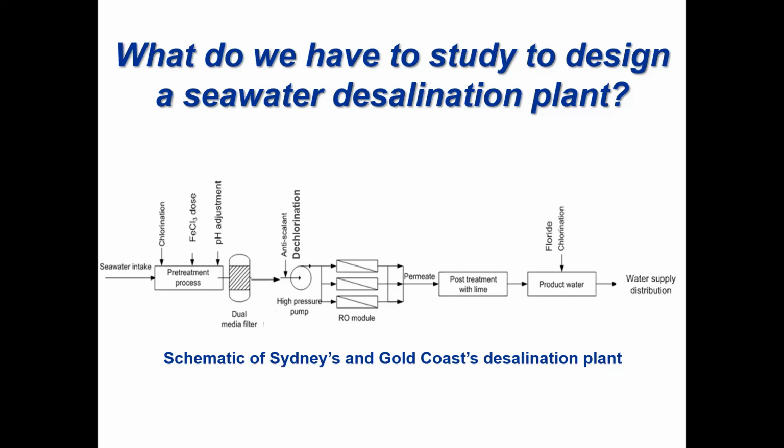We designed for 40% or 50% recovery of your seawater, so you have a very high concentration of salt. This will impact overall inorganic scaling, so we put some anti-scalant to reduce the overall inorganic scaling potential. I will talk about it in detail later, what kind of anti-scalant we can use. And dechlorination. So we put the chlorination in front of the filter here.